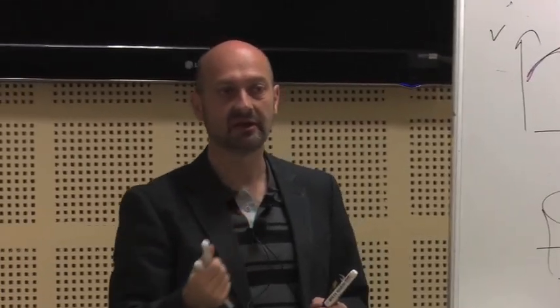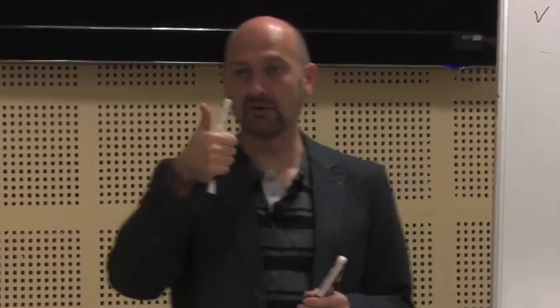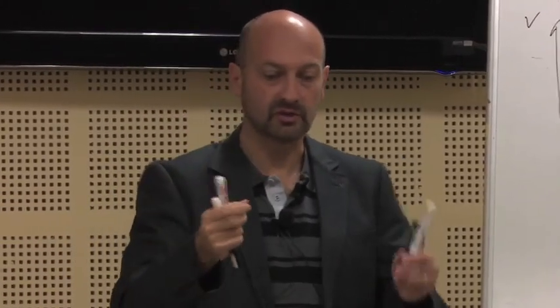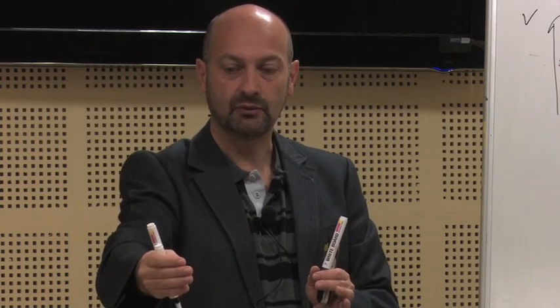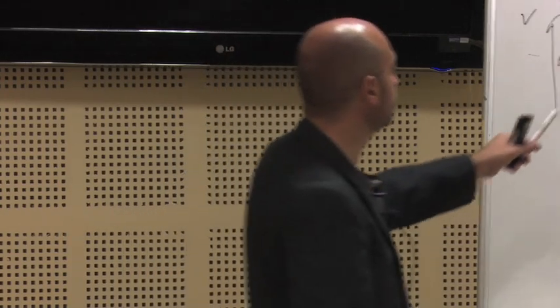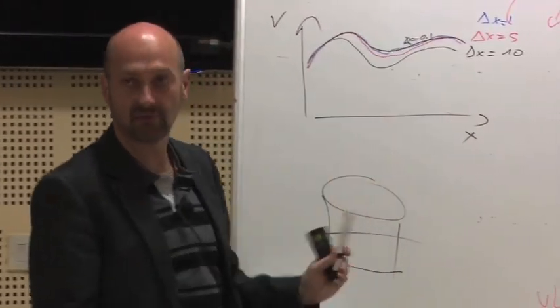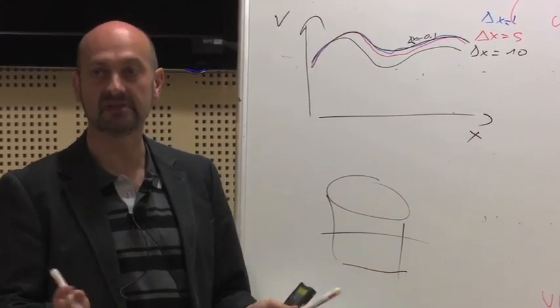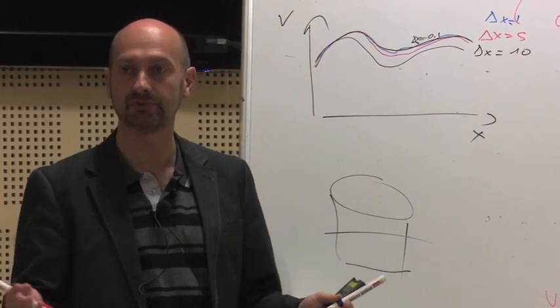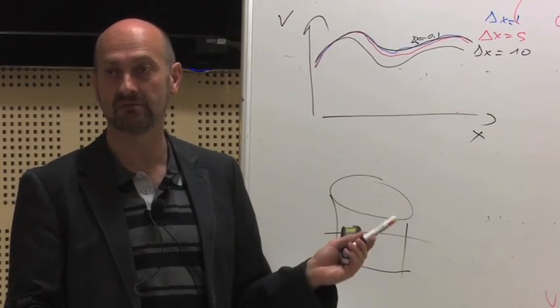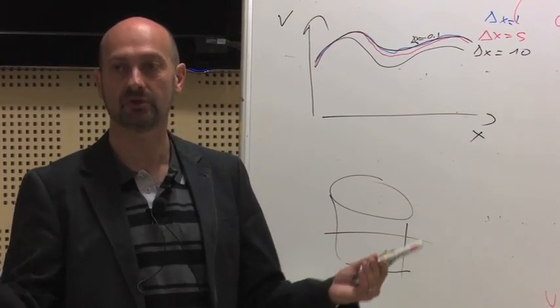So usually this convergence, you do that only on one case. You say, okay, I'm going to take these operating conditions, I run simulations with finer grids, I look at convergence, and when I obtain the convergence, let's say 0.1 is converged, so you are happy. But it is very time consuming. So you are not going to simulate all the operating conditions with the finer mesh, because that would be a huge computation.